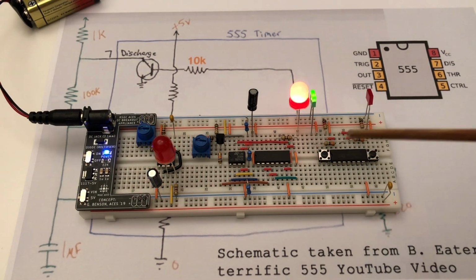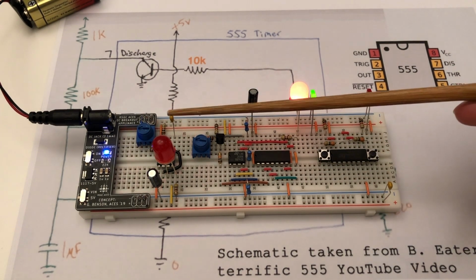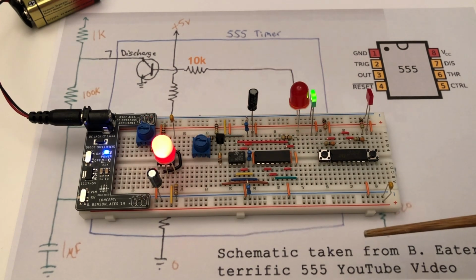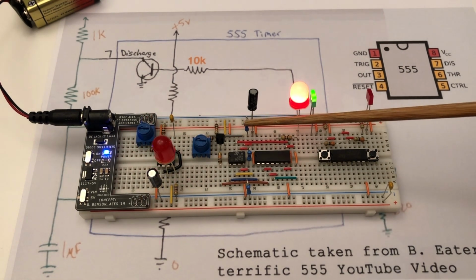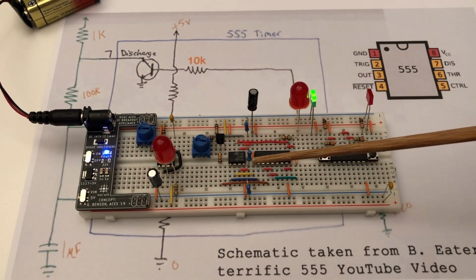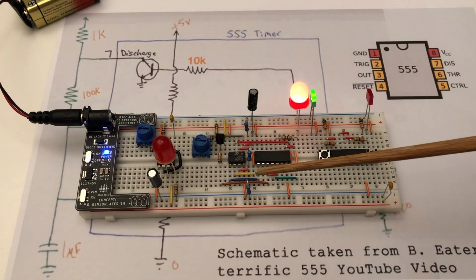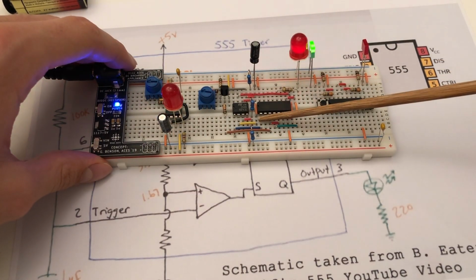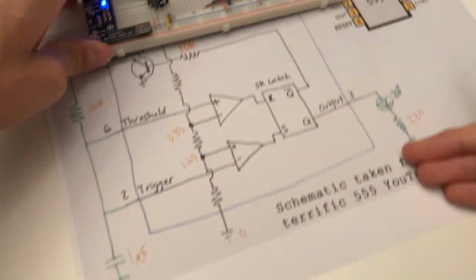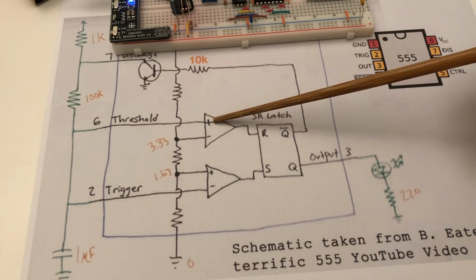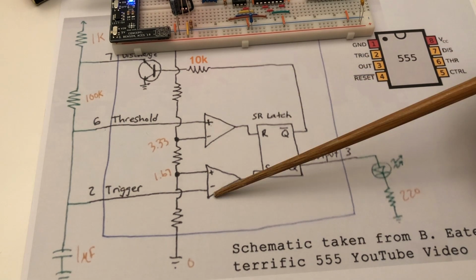This configuration provides an ongoing square wave, and these capacitors are used to clear up any electrical noise when transitioning from low to high. The name of the 555 comes from the three 5 kilo ohm resistors set up for voltage division, which is central to the function of the chip. 2/3 of the source voltage and 1/3 of the source voltage are presented at the junction points, offering fixed voltage references to the inverting input of the first op amp and to the non-inverting input of the second.